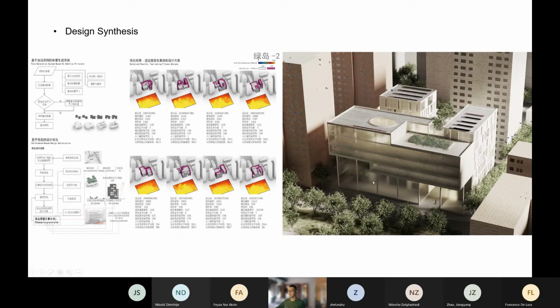So the first thing is that because the designer wants the building to have very good daylight accessibility, you can see that all the massing has a very narrow floor plan. It means that they can avoid the disadvantage of deep-plan buildings, where the central part of the building usually has no natural daylight accessibility. And the second one is that in this corner, the building will decrease its height, so it can allow more sunlight to reach the public park.